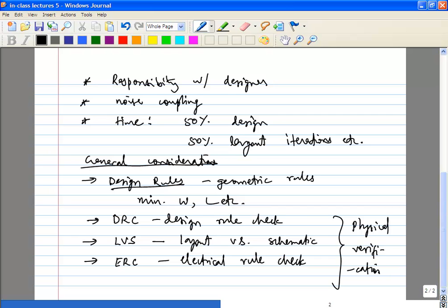Similarly, if you connect a thick oxide transistor or the IO transistor to a low power supply, what happens? You may design it for a certain resistance or a certain gm, and your VGS is going to be different from what you wanted to apply. So a transistor may have a lower gm. If you are using it as a switch, it may not turn on enough.